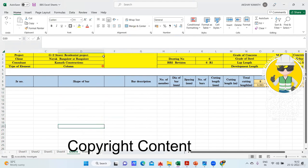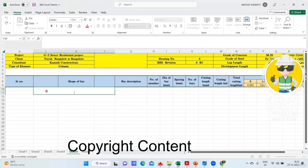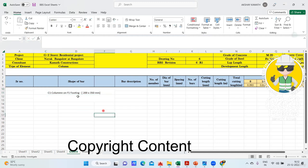After that we can reduce this size a bit. The first thing I need to write is C1 column on F1 footing. Why am I telling you to write this? Because it is easy for us later. 200 by 350 is the size of my column. You write this also, so that every time you don't have to look into the structural drawing.